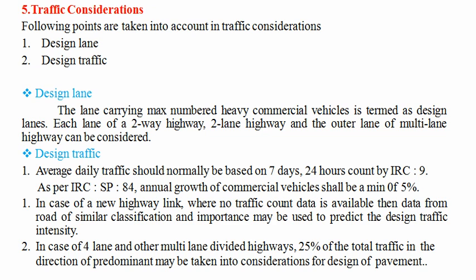For the design traffic, the average daily traffic should normally be based on the 7-day 24-hour count as per Indian Road Congress section 9, and as per the Indian Road Congress, the annual growth of commercial vehicles shall be a minimum of 5%.